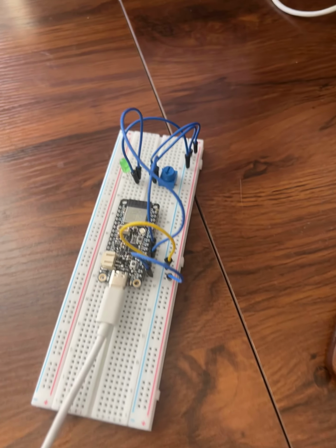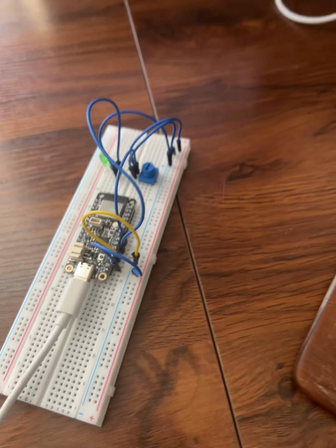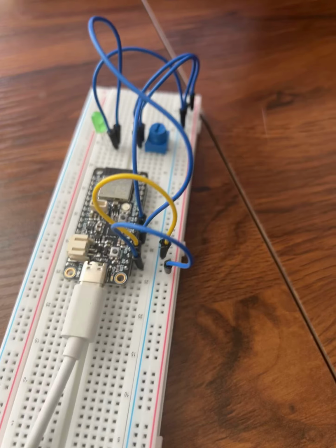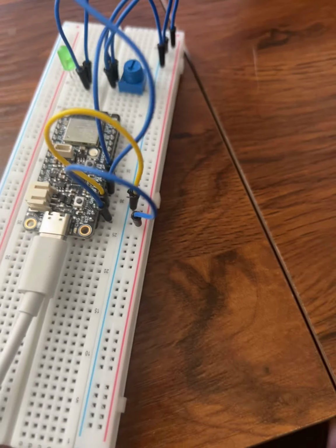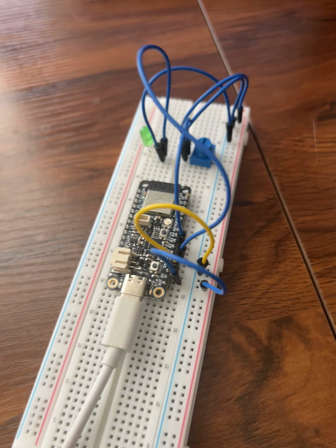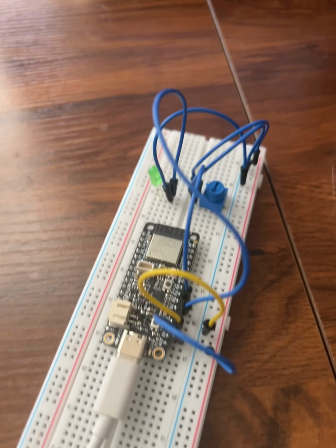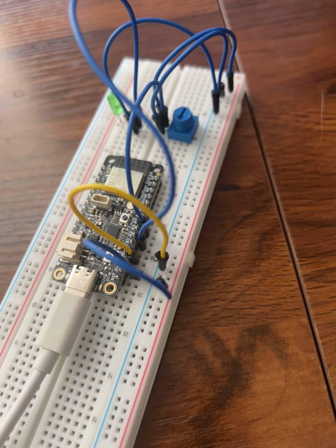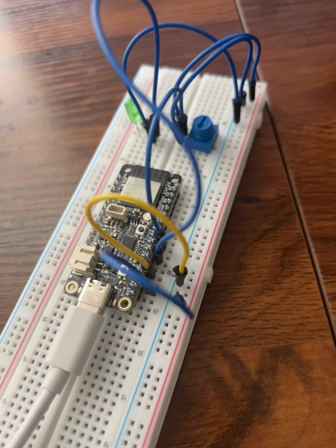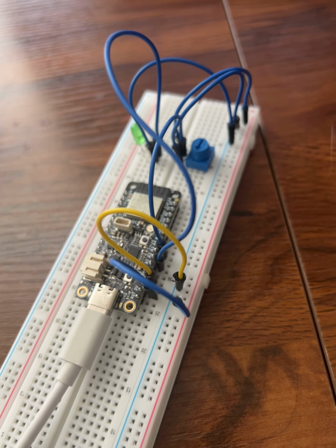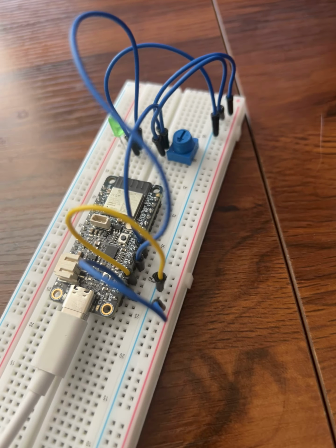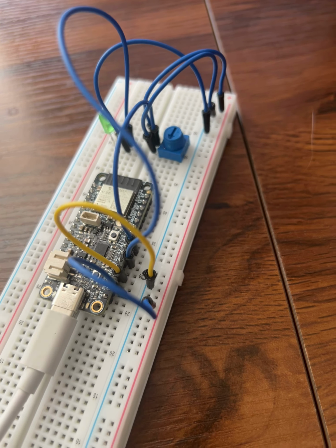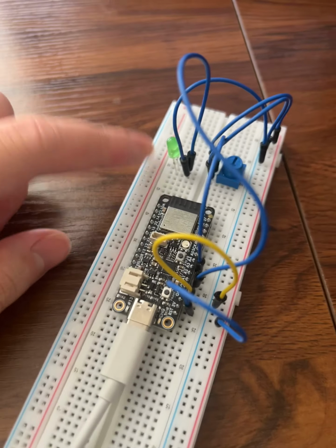So I want to quickly go over my LAB2 setup with you guys. First of all, I'm connecting my potentiometer to pin GPIO 39 on the ESP32, which is pin A3. This pin serves as an input pin to receive the ADC value from the potentiometer, and then transform it into digital value so that the system can process that to change the frequency and duty cycle of the LED light over here.